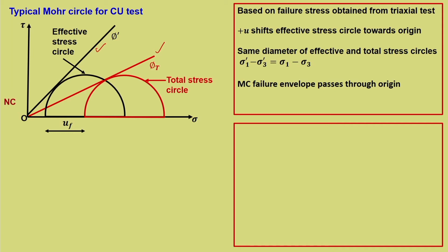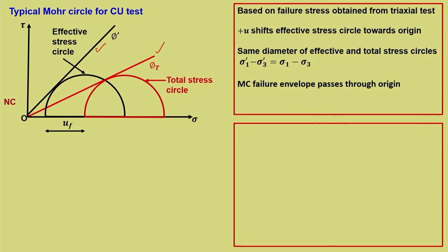Let us say that you are dealing with normally consolidated clays, and if we have a certain wrong notion that clays are always cohesive material, then we tend to question why there is no cohesion and there is only friction, which may sometimes be difficult to understand. We need to understand that all soils are granular in nature and can mobilize friction. Now, what happens to a normally consolidated material?